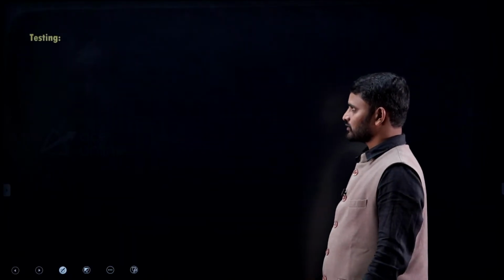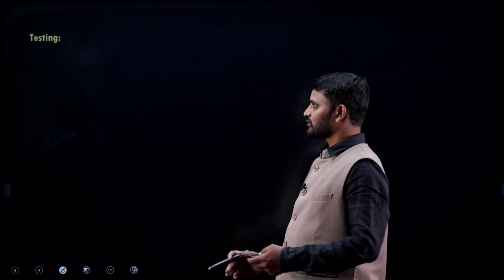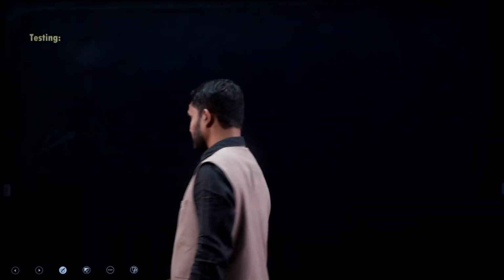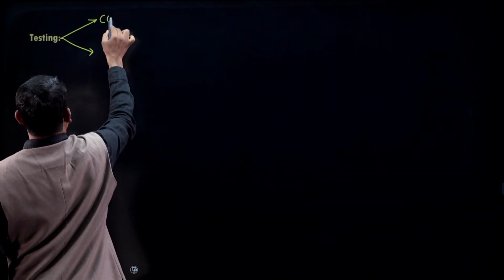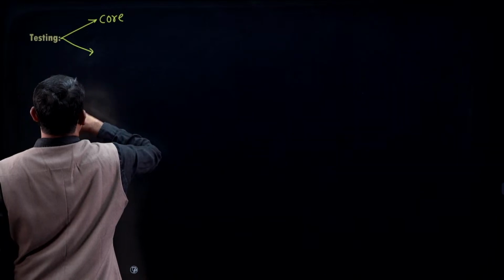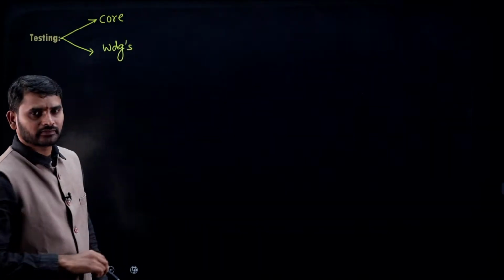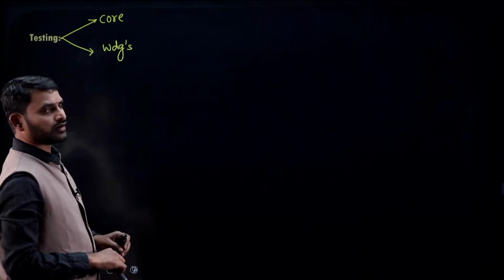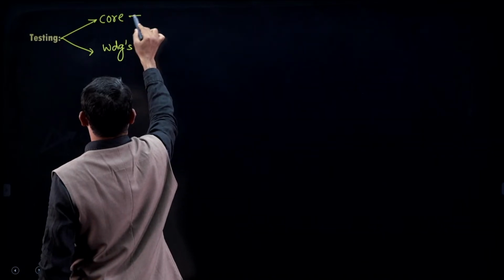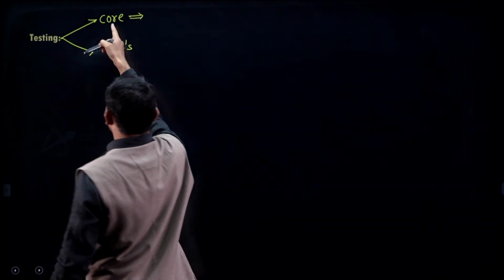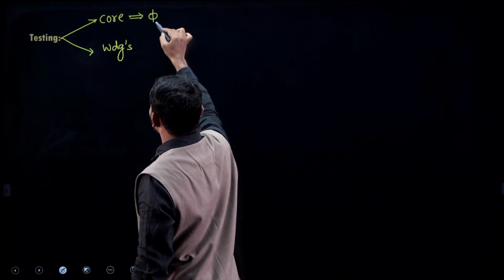Okay. Those are some questions on operation, and coming to testing, we will see testing. The major transformer parts are core and windings. If you want to test the core, you will conduct the open circuit test. How to test this? The core's purpose is to carry the flux lines. So you have to test the core at rated flux.